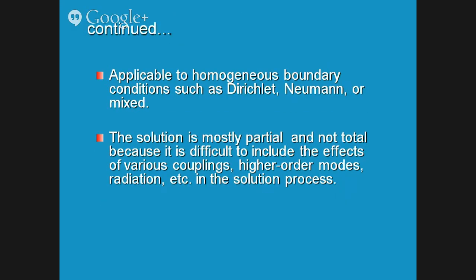Okay. Then there is the boundary condition. They should be either homogeneous boundary conditions like Dirichlet, Neumann, or mixed type. Inhomogeneous boundary conditions cannot be taken care of. The solution is mostly partial and not total because it is difficult to include the effects of various couplings, higher modes, radiation, etc. in the solution process.